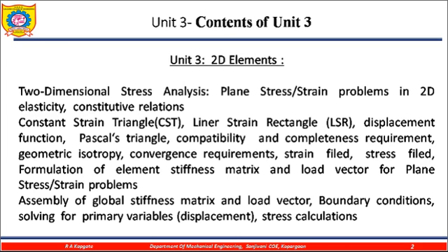Here we need to first define the displacement function for 2D, and when we are developing the shape function, the relationship of the displacement function is to be considered through the Pascal triangle. We also study compatibility, that is the continuity and completeness requirement, as well as geometric isotropy. We need to work on the convergence methodology, strain field, and stress field.